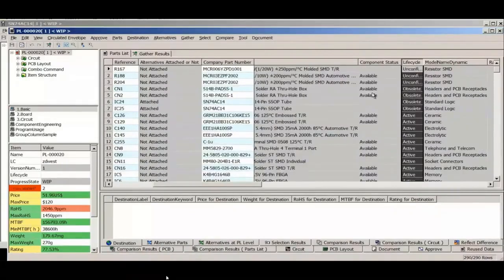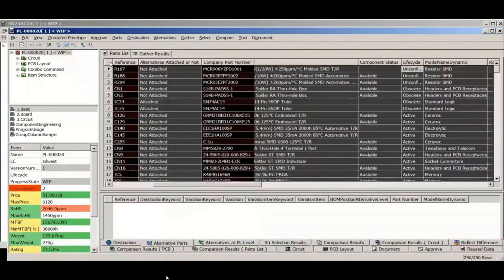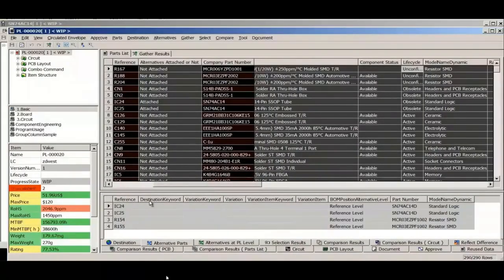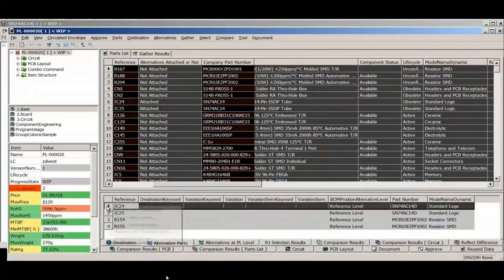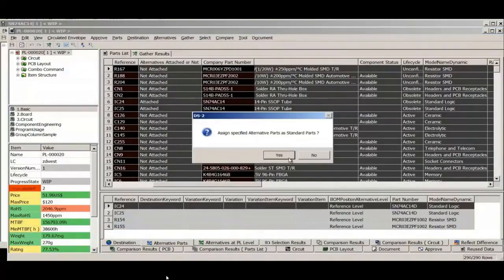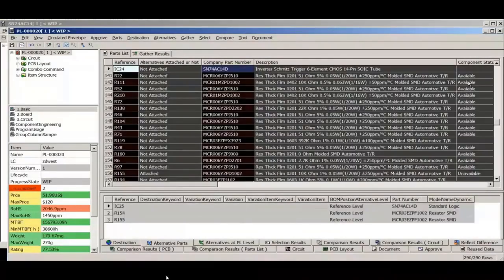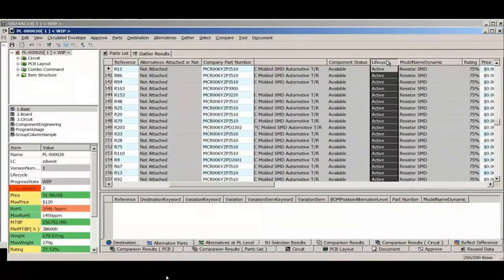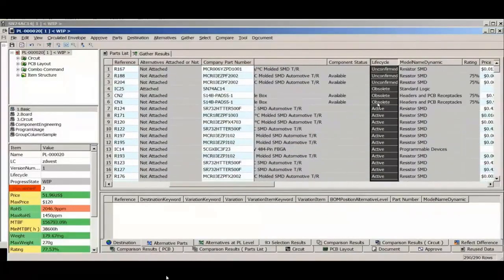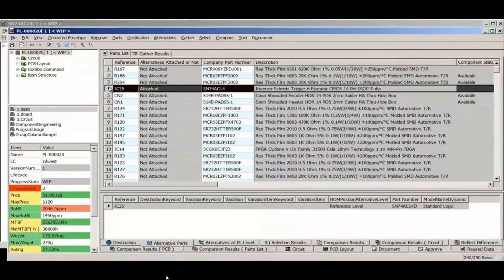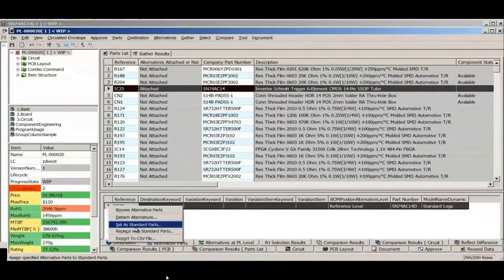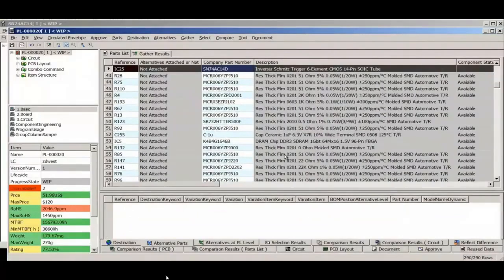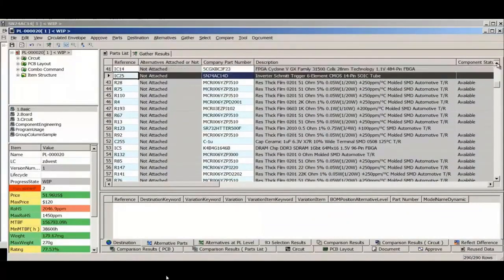We're just looking at the bill of materials and automatically updating the parts in a particular project through the system here. So we've marked it. We can see here 2 of those 74AC14s are utilized in this particular project, IC24 and 25. And we can select the ones that we want to find the alternative parts for, or specify the alternative parts. So in this case, we're going to address IC25 just to show how this is done. And we're finding the alternative part and assigning it through the text-based system here, through the spreadsheet.